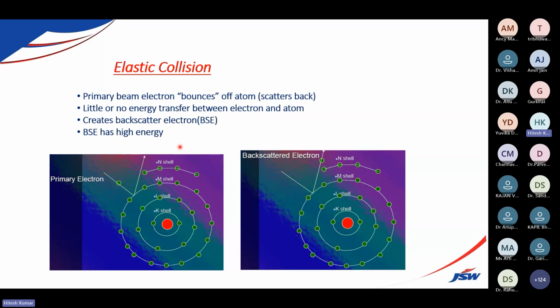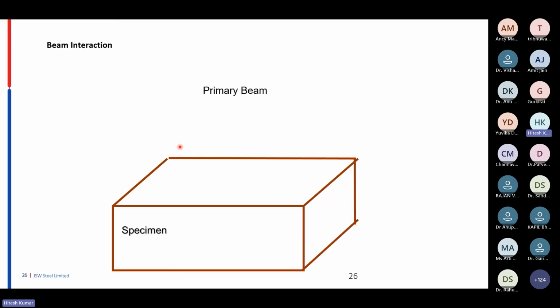So let's suppose you have a sample which has two different phases, and you want to know the phase fraction of one phase to another phase. Then you have to go for the backscattered diffraction method. Scanned electrons will not give you that much good information. For that, you need backscattered electron information. That will give you a more appropriate idea about the phase distribution inside your material.